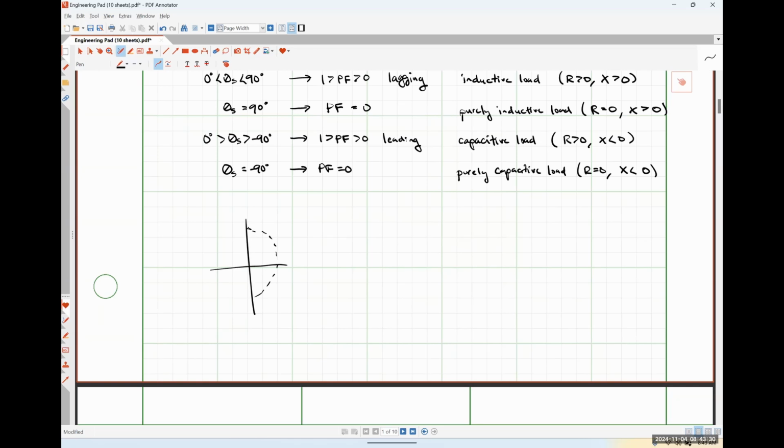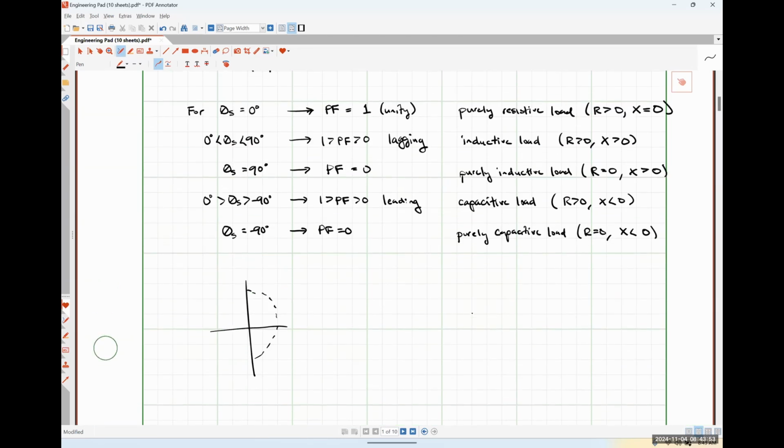Negative resistance is definitely a possibility. In fact, these might be LED lights up in here, but our fluorescent ballasts that we use to power fluorescent lights actually operate like they have a negative resistance. Literally, all that means is that as you increase the voltage, the current is flowing in the opposite direction you would expect. That's all negative resistance means. But anyway, we're going to limit our cases to plus or minus 90 degrees as our maximum value instead of plus or minus 180, because we are not going to bother with the negative resistance cases in this class.